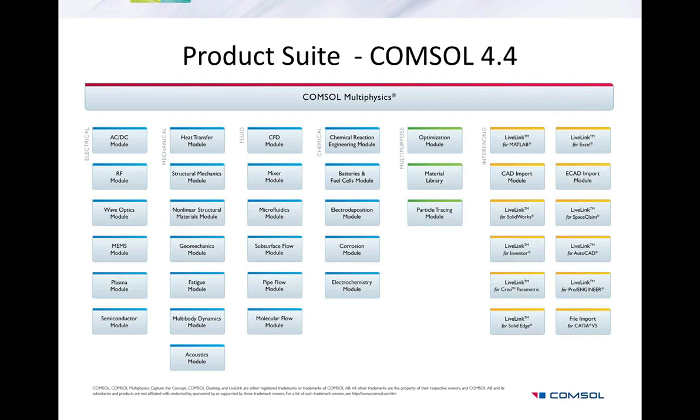And in general, which mesh type would you recommend, or it doesn't really matter? Well, if it's possible, it's always or usually better to use a structured mesh. But in many cases you can't do that, like when you have complicated geometries.